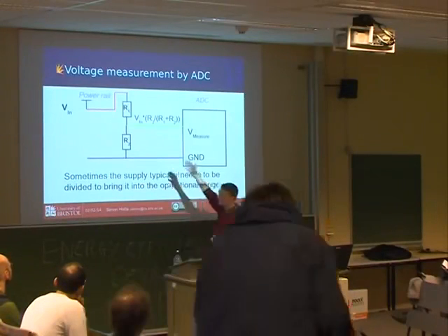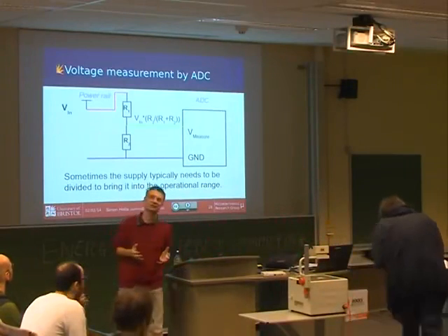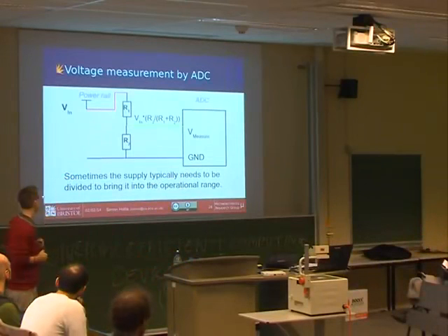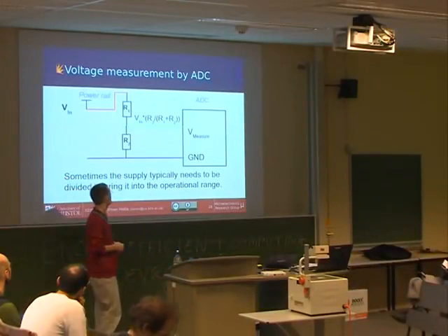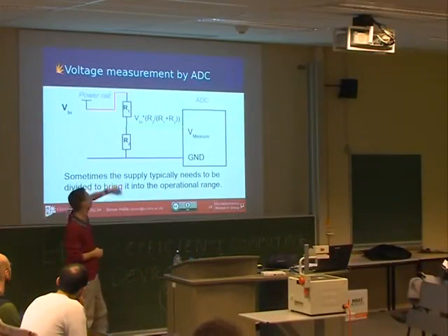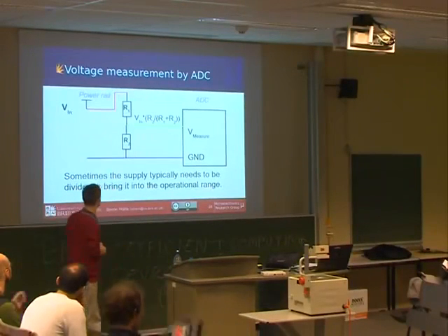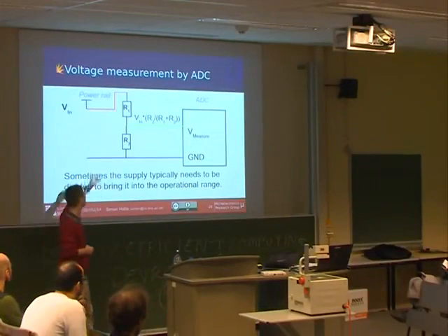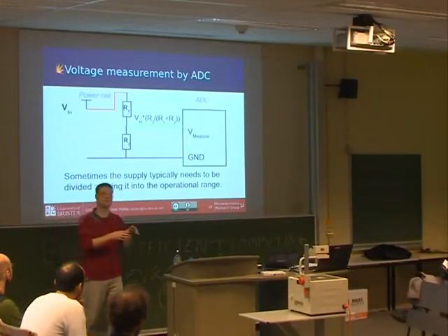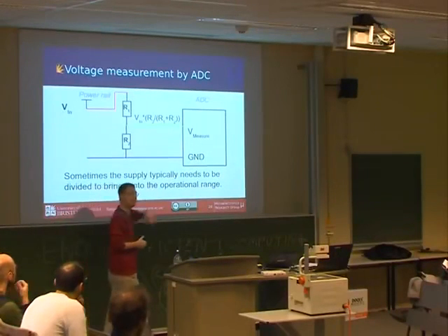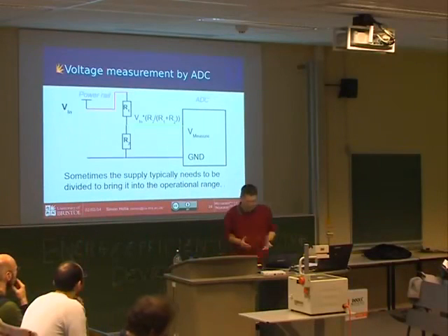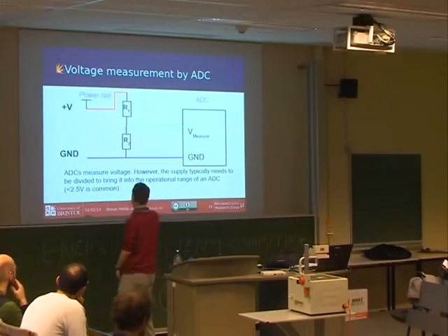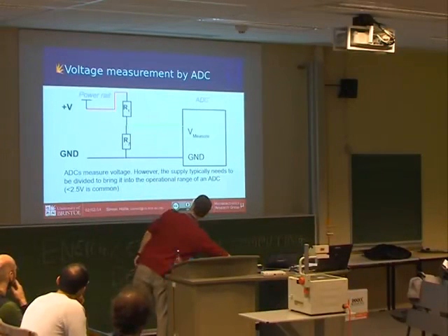So the first thing we want to do, we build this structure called a potential divider, it uses 2 resistors, and that allows us to drop a high range of voltages into a smaller range. And it's determined by the equation that's up there, and V out is the voltage in times the ratio of resistors. So if we want to halve the voltage range, so we have 0 to 5 volts, we put two identical resistors in there, we'll get 0 to 2.5 volts. And then we bring in this range of units. So that's nice and easy. And we'll do that when we need to.